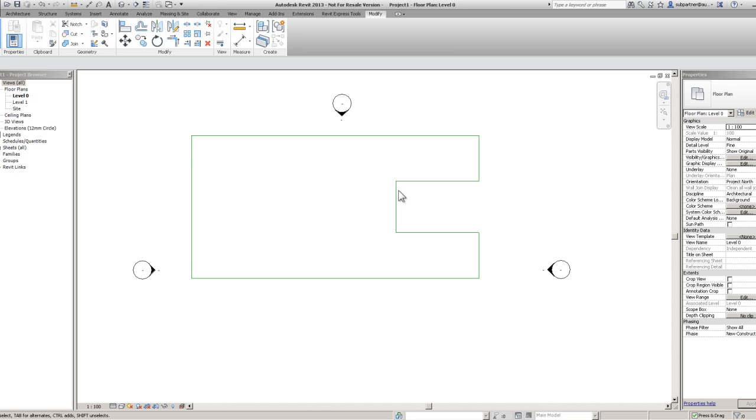Okay. Right. Last couple of things. Curves, arcs, that kind of stuff. Obviously, you saw us do the trim earlier on, trim and extend the corners, which is kind of replacing the fillet at a 0 radius in AutoCAD. Now, what if we want to do a fillet without just bringing it to a point, doing it at a 0 radius? What we can do is this.